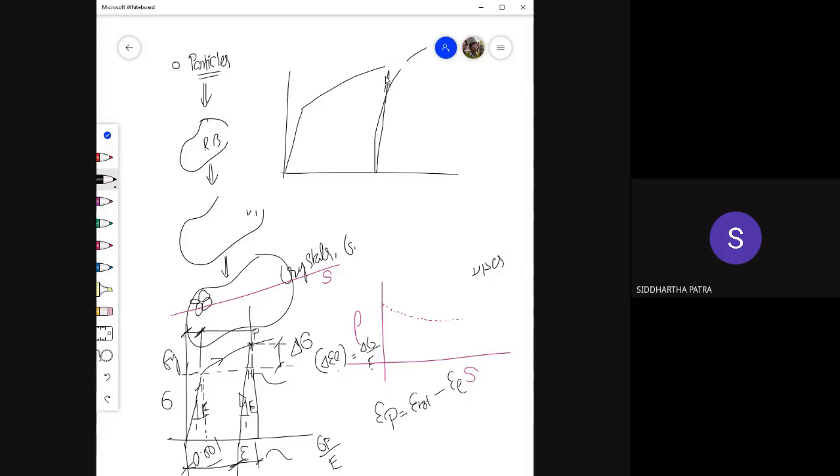And what is supposed to happen is, it is also supposed to yield from the stress from which it has been unloaded. But that's not exactly what happens. It follows a slightly different curve on reloading. So there is loading, there is unloading and reloading. They are very different curves. Those are the actual material behavior. That is how nature has created the material. And to be exactly able to model that, we need better models.